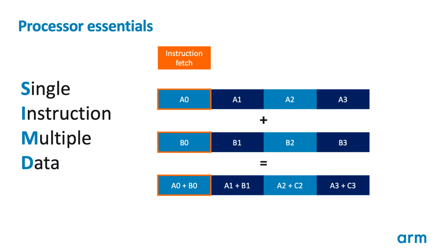One concept from CPUs that is useful is the concept of vector processing hardware. Most application processors have some form of vector instruction set, such as the ARM Neon instruction set, which expose vector operations to software. For the cost of managing a single instruction, we get multiple data processing operations, amortizing the energy cost of the instruction control overheads, and making the overall processing more energy efficient. This is an idea that we'll come back to, as energy efficiency is what the GPU really needs.